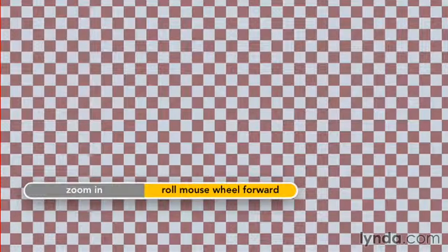I'm going to use the modify tool. It's a little tough to see what I've got here. So the scale down here is set to 1/2 inch. You can change that to anything you want. Doesn't really affect the family in any way. So I'm going to make it 1/4 inch equals a foot and zoom in a touch so that we can get a better look at what we've got.